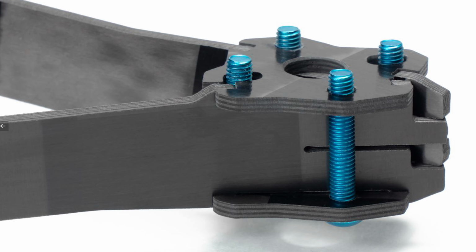The longer you cut, the further down this tool gets, and then you can see that now I need to compensate, like, 2 microns more or whatever, so that we can be extremely tight in tolerance during these batches, so that one arm from one batch to another will be super tight. We don't test the parts to each other when we set the tolerances in this water jet. We test them to this master guide, so that all parts will always fit into each other, even between batches.